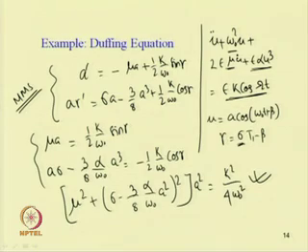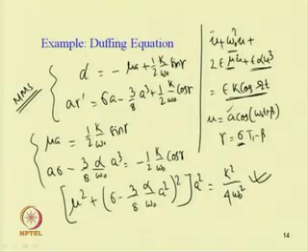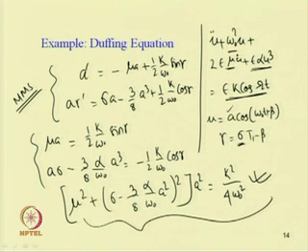We have seen the solution of this equation equal to A cos(omega 0 t plus beta), so this amplitude A and the frequency are related by this equation. In this equation we have sigma, which is the detuning parameter that shows the nearness of omega, so omega will be equal to omega 0 plus epsilon sigma.